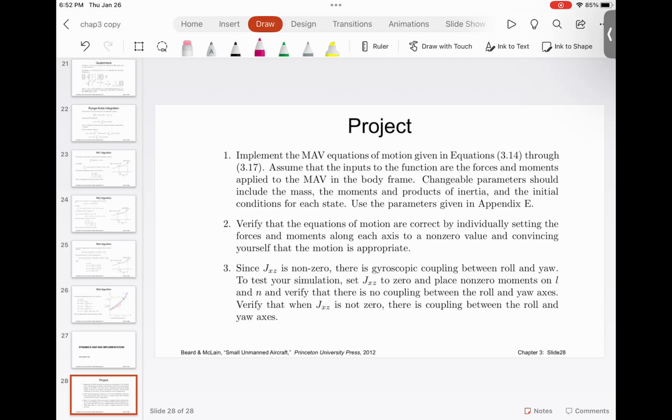Even so, rudder is supposed to make it yaw. But what happens is when the aircraft starts yawing, because of the coupling, it tilts. It's an under-actuated system. If you look at the dynamical equations of motion, the easiest way to show that to you is to run that in simulation. Part of it is because the rudder is above the center of gravity, so when you exert force there, it twists the entire body.